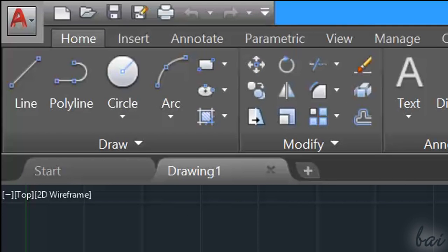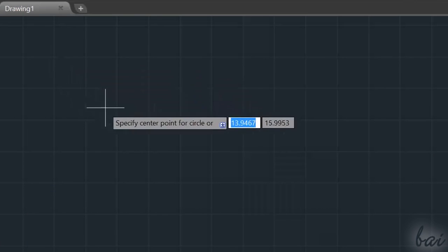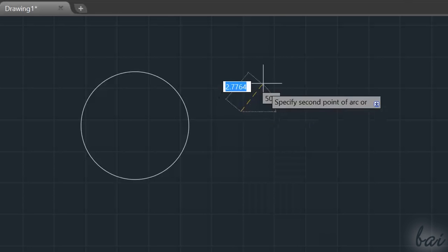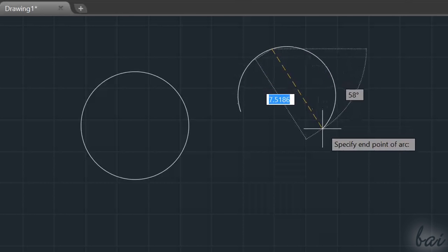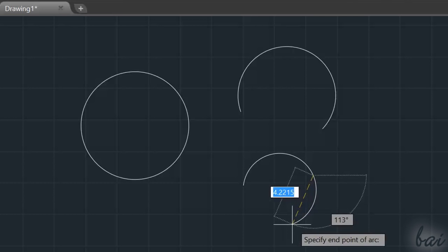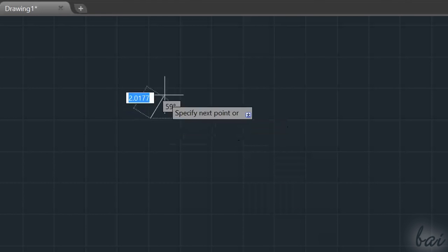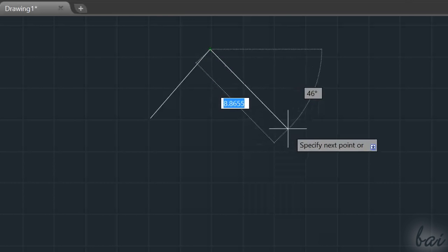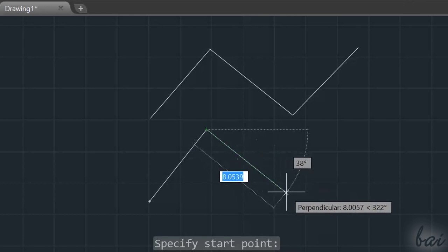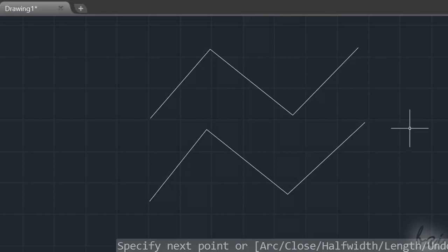As seen in the previous beginner tutorial, the Home section collects all tools used to draw objects in 2D. The circle, the arc, the rectangle, and the ellipse tool draw just one object at a time. You can use the Enter key to enable the tool again and draw another object. Whereas, when you use the line or the polyline tool, you will go on drawing sides and curves continuously, sharing the last fixed node. To stop drawing, use the Escape key.